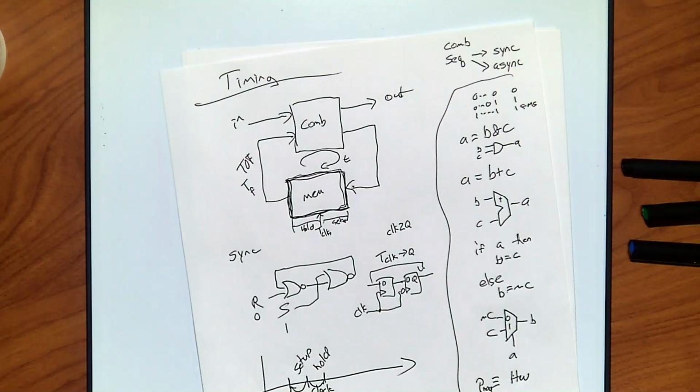If I have just one time constant, RC, you're going to get C from the capacitors within this and between wires and all kinds of stuff. So there's some net capacitance, some resistance down the wire, right? How much does one time constant allow the signal to change?